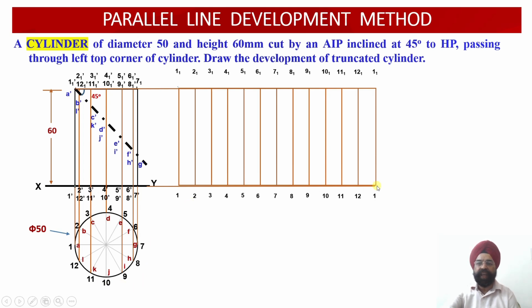But in engineering drawing we are not allowed to use mathematics over there. So we use the method of construction to draw different points. If I have to measure this arc length, I don't have any instrument. Ideally I should have measured the arc length. So what I am measuring, with my limitation, using my scale, is the chord length, that is the straight line distance between point 1 and point 2. So this will be shorter than the arc length.